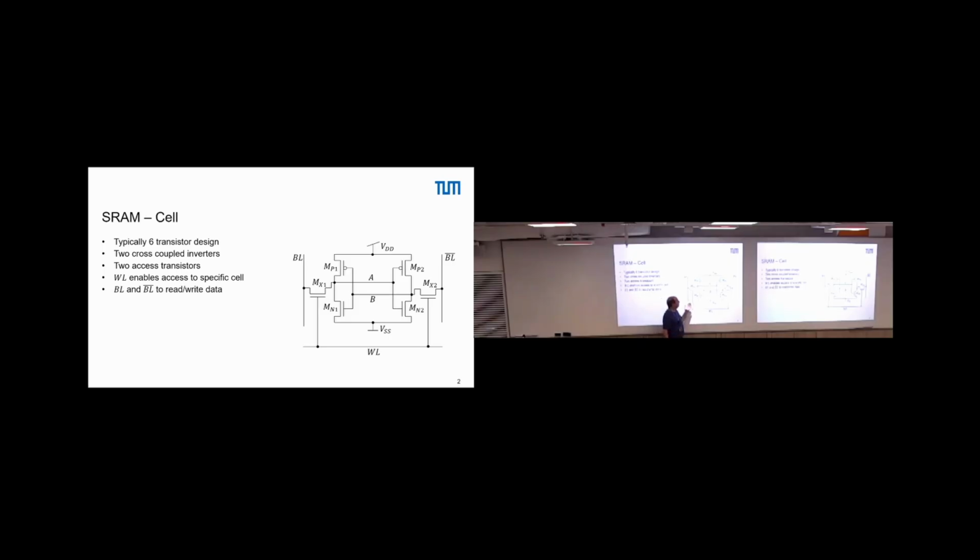Now if you preload bitline to a specific value, enabling the switch would also impact the value of A. And if this impact is too large, then what we had drawn before, these lines, say that if we go over the metastable state for a tiny little nanosecond, picosecond, whatsoever, immediately this thing will flip.